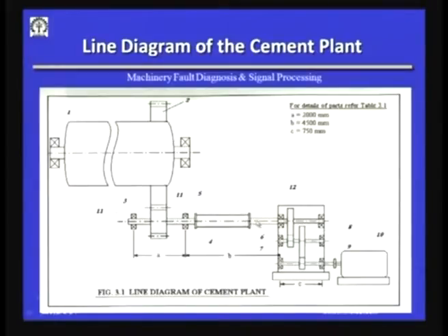And then there is a torsion shaft here, and this is the weakest member. So, if there is any failure, the torsion shaft will shear and fail. This is just a safety measure, in the sense that we do not want any of the bearings or the gears to fail, but just let this torsion shaft shear. And then, sometimes this is held by plummer blocks here, and the problem here is the bearings in this gearbox.